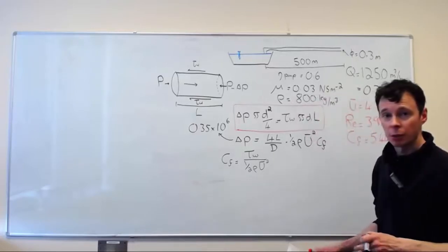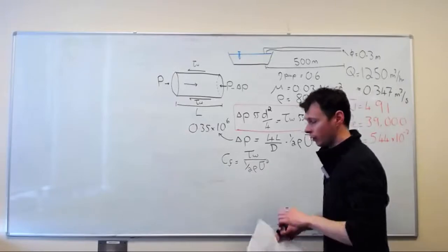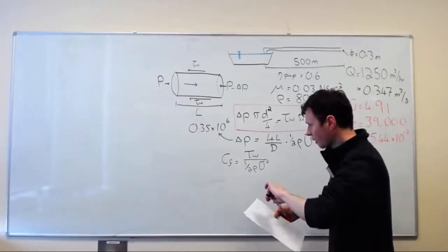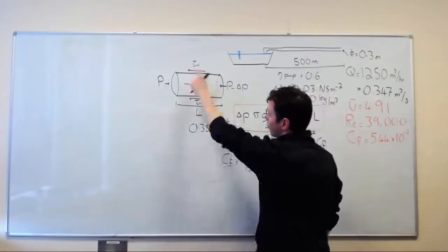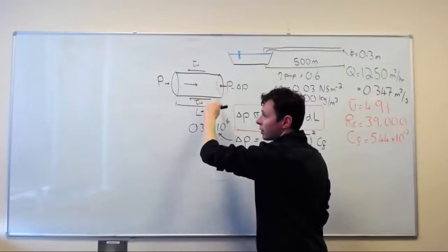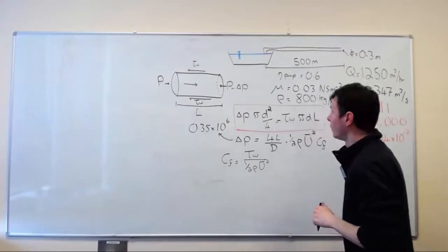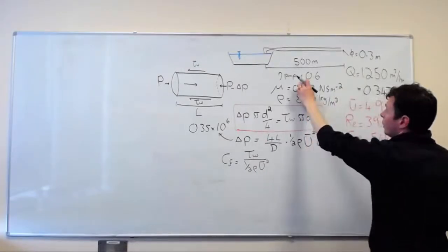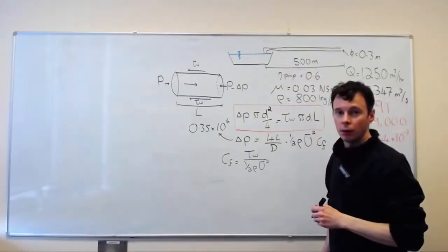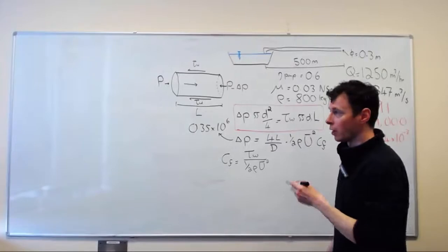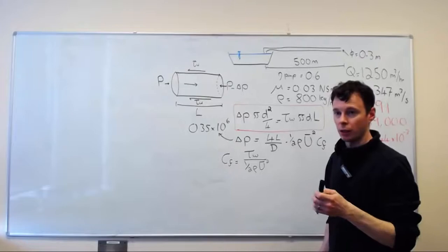So now we've found the delta pressure term, we need to do an energy balance. So if you go back into your notes, the energy required is going to be equal to the energy to overcome this internal friction plus any kinetic energy out. And then we've got a pump efficiency here. So the pump's going to have to deliver more energy in than we get out. So you need to divide that energy in by 0.6 to give us a greater number, so a greater amount